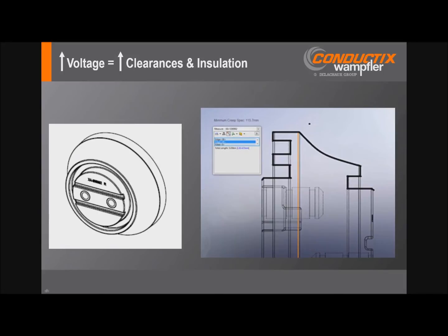Essentially those are mechanical strength, both under normal conditions and also fault conditions if there are some expected, as well as providing the adequate creep distance in the specific environment. And that creep distance essentially is this black line, the distance from the live conductor to grounded surface.